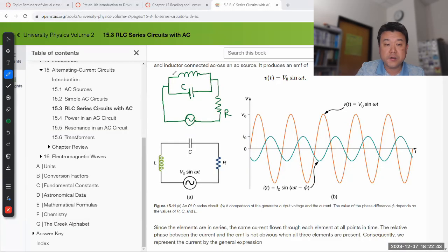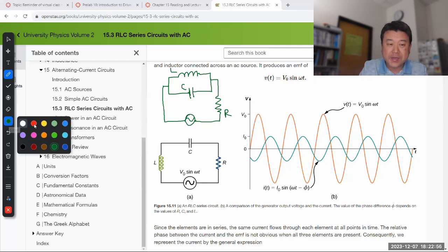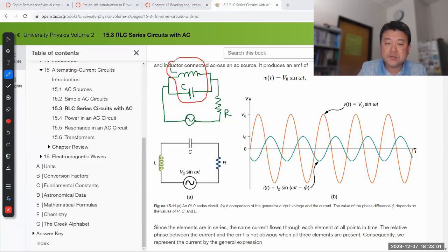So this would be another example of a driven LRC circuit. Now, as you look at this and try to figure out how to do that using phasors, you can't really, or you can't do it easily, because in order to do this analysis, you need to add these elements in parallel. And you haven't been given a rule for how to add phasors in parallel. I think I figured out that rule at some point, but it was so complicated that it wasn't worth using. So that's the limitation of your textbook approach.